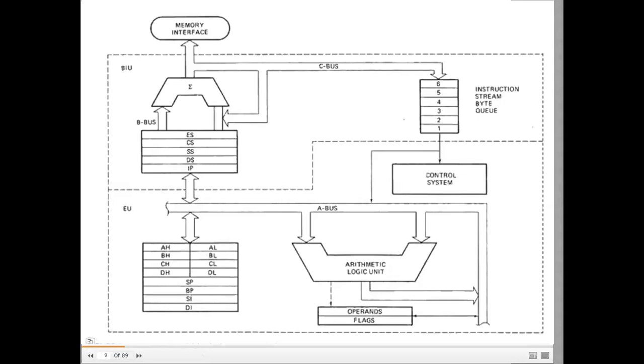There is one arithmetic logic unit which performs the arithmetic operations. Once an arithmetic operation has been performed, it can have an overflow or underflow, or it can get a sign, and so on. Therefore, these are referred to as flags. By seeing the flags, I can understand how the arithmetic operation has gone, so that I can compute and modify my data so that it stays within the range of operation.